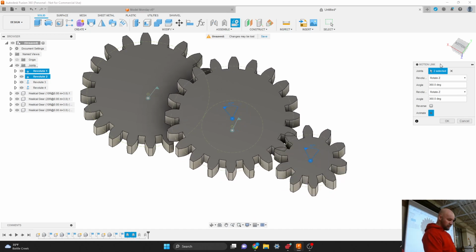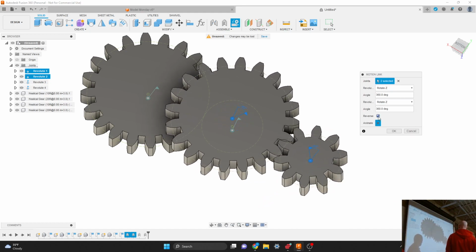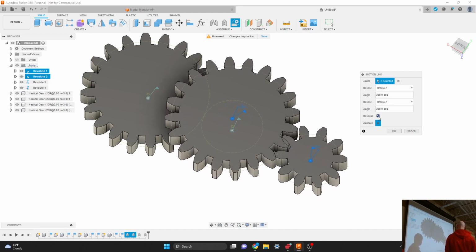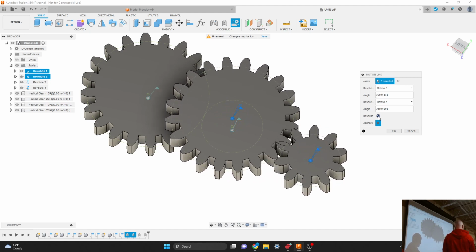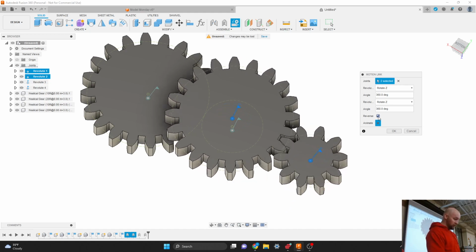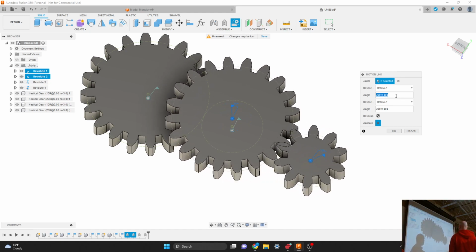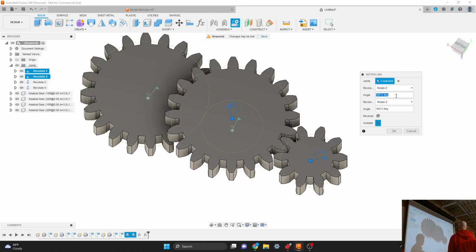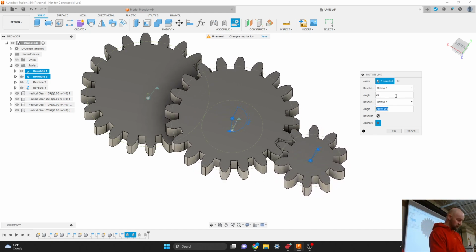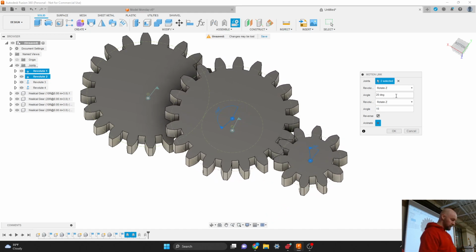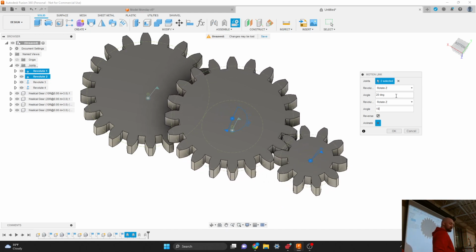because these are meshing with each other, we have to do a reversed joint. But you'll see here, they're moving incorrectly. This gear is actually rotating around half as fast as this one is, because there's a reduction going on there. Well, actually the easy way to do it here is just to pick the number of teeth in each of your gears as your ratio. So I'm pretty sure if I do 20 and then 10, yeah. So then they mesh correctly. And they go super fast here.